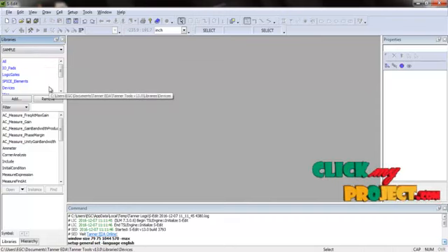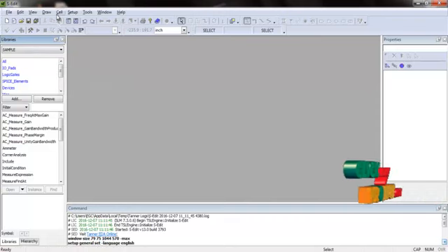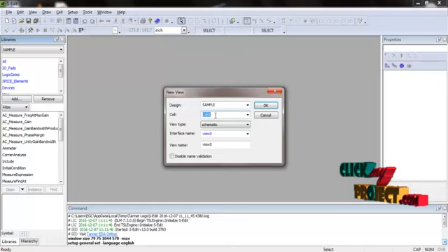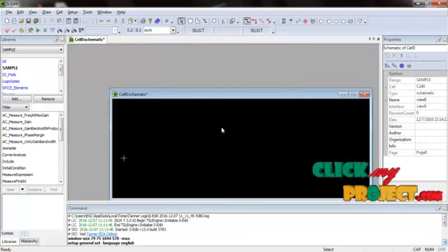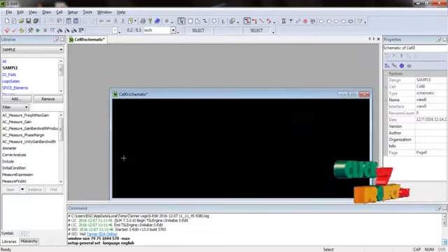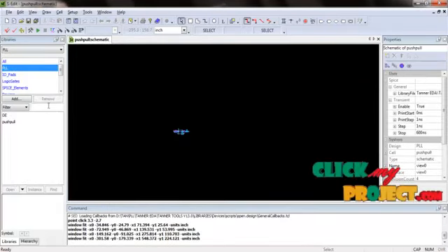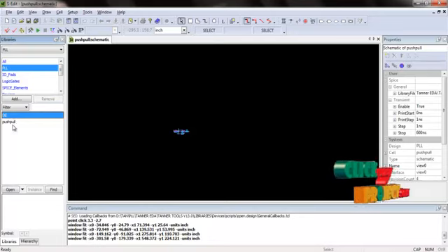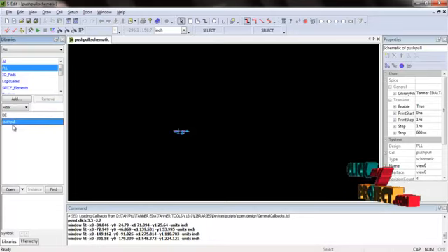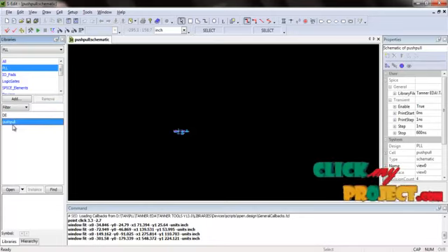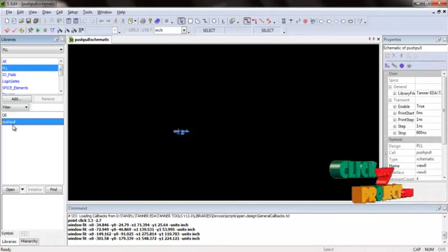Now start the schematic using the cell option to create a new view. To assign the cell name, or else it is assigned as the default cell 0. Click OK to continue the design. In our product we are using two different cells. They are named as DE and push pull. Both are different voltage controlled oscillators for phase lock loops.